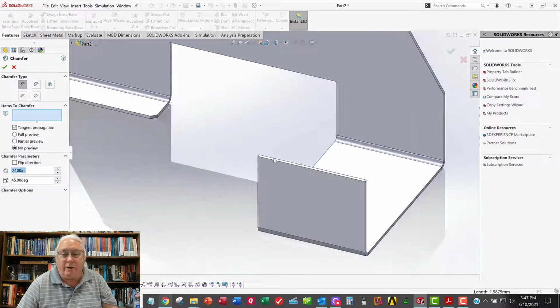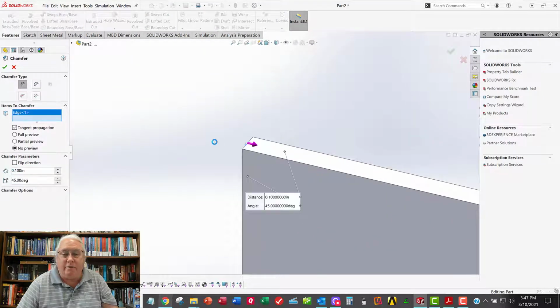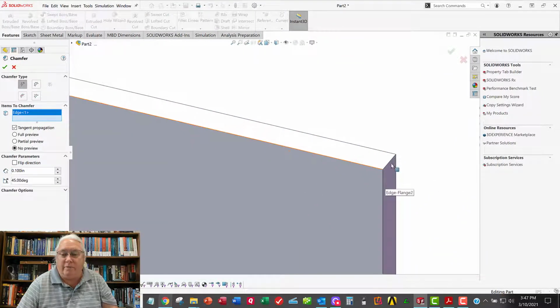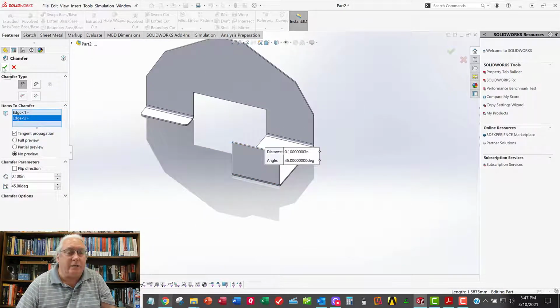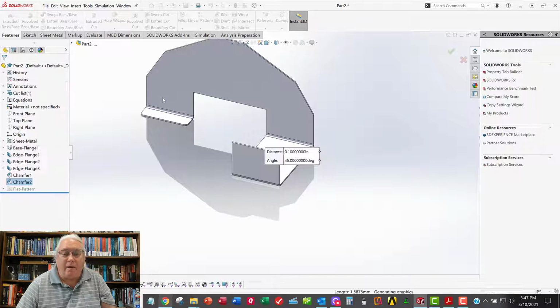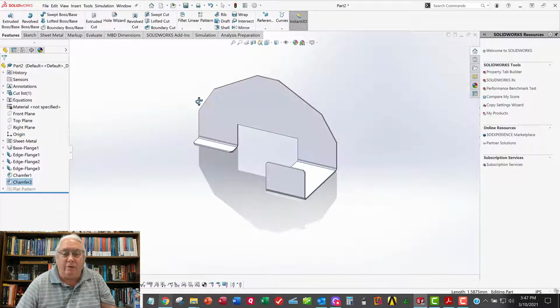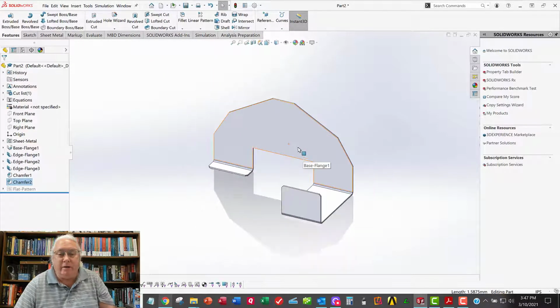So even though this is a sheet metal part, you can still use those other familiar SolidWorks features to do tapped holes or through holes or cuts and extrudes and things. Alright, so I'll let you worry about getting those other features on there. So now let's see the magic of how to make this flat pattern.